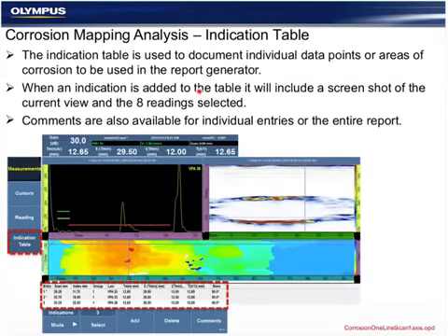The indication table is populated exactly like the UT for weld inspection. We optimize all displays and cursors, and display the relative reading representative of the low point, and either from a right click on the title bar or using the menu for the indication table, defects are added to the database and recorded and printed.